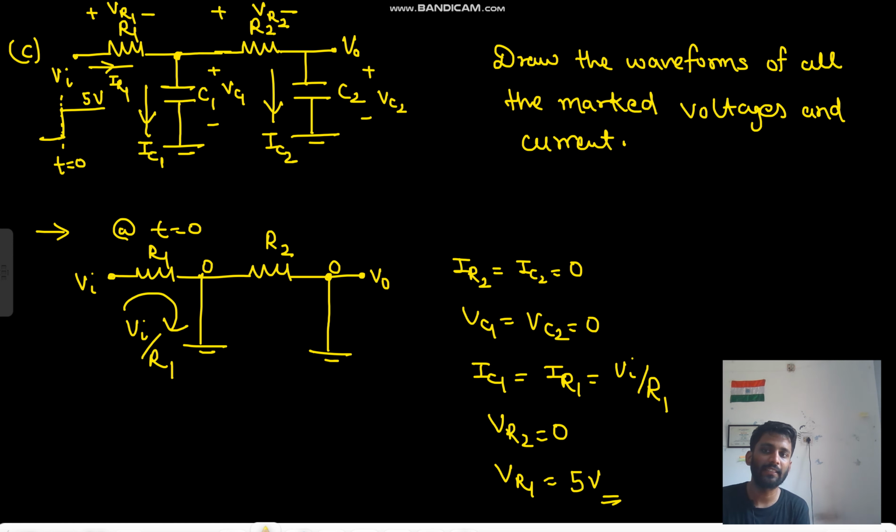Look, C1 is getting charged with this IR1 equals to IC1 plus IR2. Okay, so your IC1 would be IR2 minus IR1, right? No, IC1 would be IR1 minus IR2, because IR1 is equals to IC1 plus IR2. So your capacitor C1 is getting charged with IR1 minus IR2. Your IR1 is always greater than IR2, because in this case we know that the voltage will always increase.